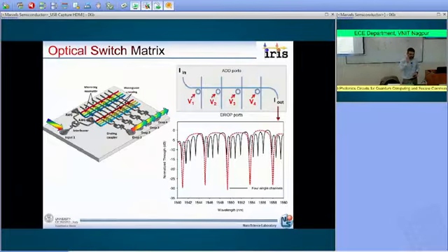From the design point of view, they all have the very same radius, 10 micron. But the actual fabrication, caused by the finite resolution of the lithography, makes the spectral position of each one slightly different. And this is something that we cannot accept, because in our matrix we have 100 of those microring resonators. So we need to very carefully align all of them.